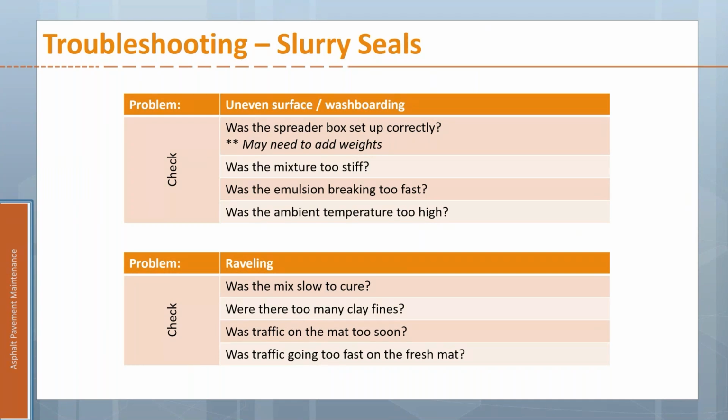If you have raveling, then the mix might have been a little bit too slow to cure. You might have had too many fines. Traffic could be on the mat too soon, or it could be that it's just going too fast on that fresh mat.